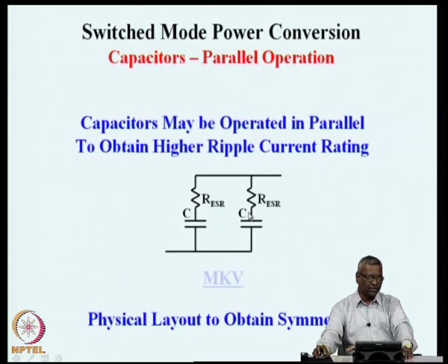When capacitors are connected in parallel, one more essential precaution is that the high frequency currents are now going to be decided by the ESR values. The ESR values as per the catalog may be equal, but if your connection has non-ideal contact resistances or conductor resistances, it is necessary to make sure that those paths are also identical.